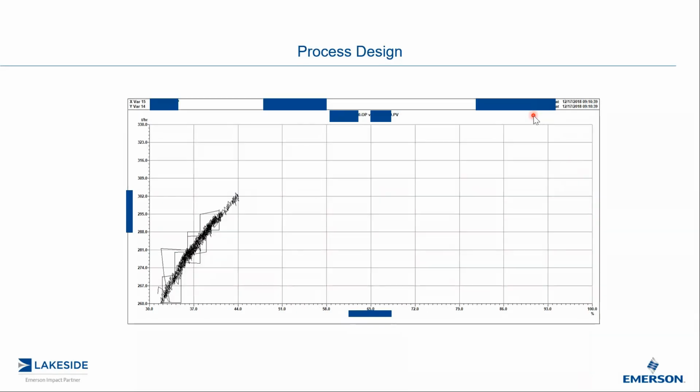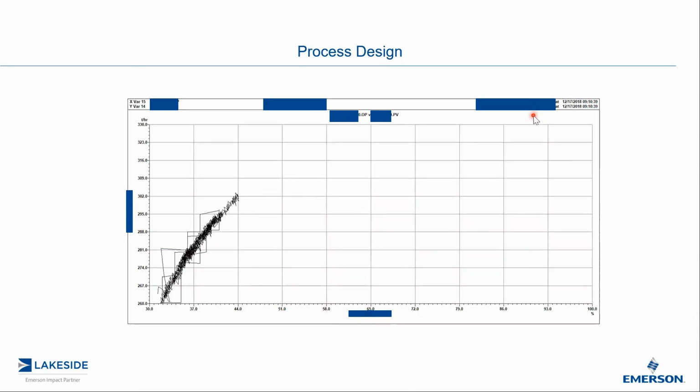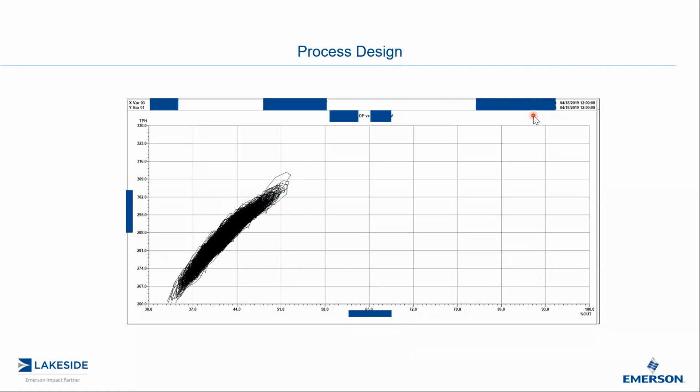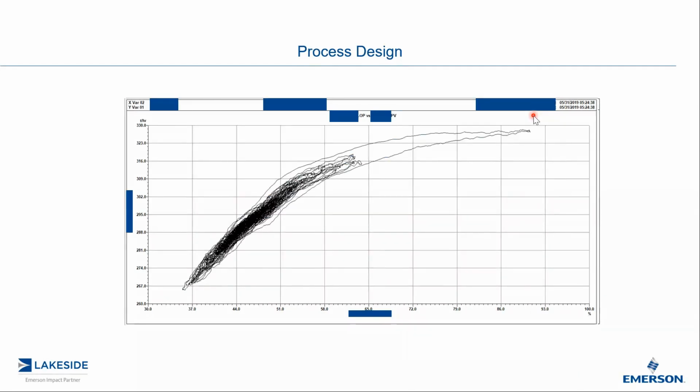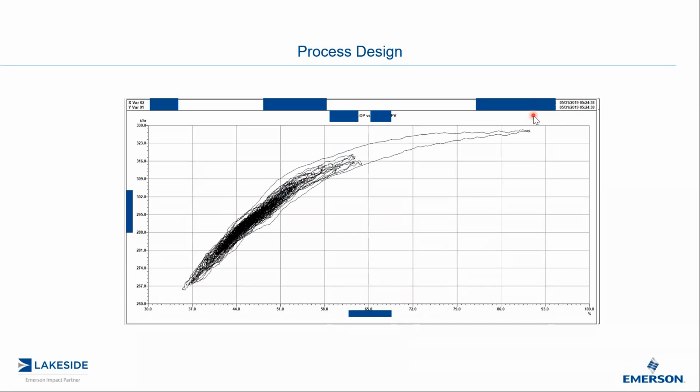If I flip back and forth, you can see the curve is getting a little bit lower. And then after that, I measured it again in May. And if I go back and forth, you can see that the pump curve is, this is my technical term, wilting. So the pump is actually wearing out. These are not very off-the-shelf pumps. This is a pump that takes probably 52 weeks delivery time, a full year delivery time.